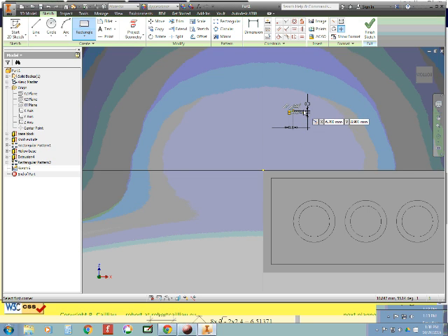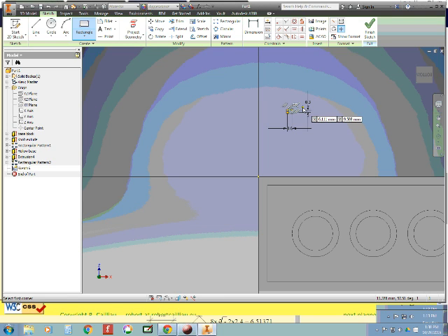And again, it has all those constraints turned on. I don't want to see those, so F9 will turn them off. And then, oh, we're already out of the Rectangle tool. That's good. Now we need to dimension, or we need to locate this. So I'm going to bring it down here onto our drawing.